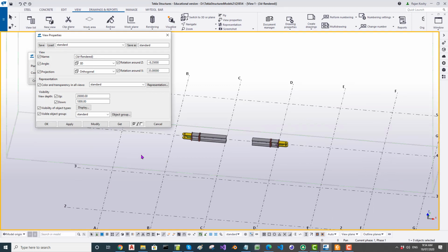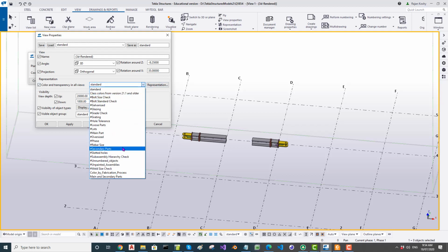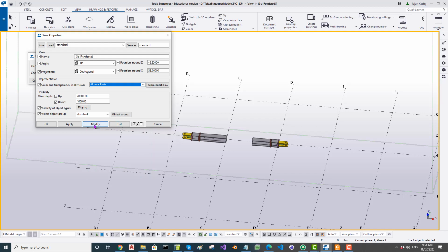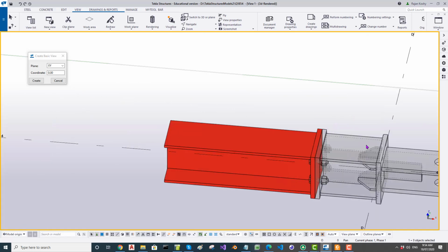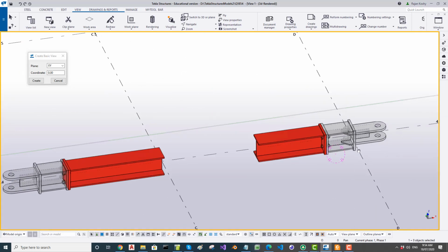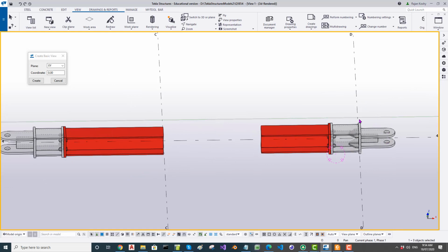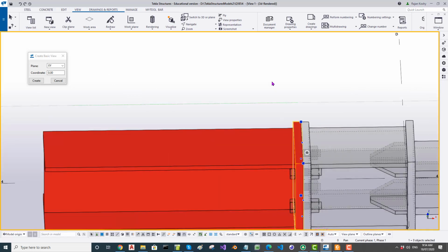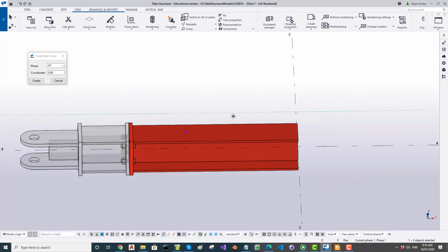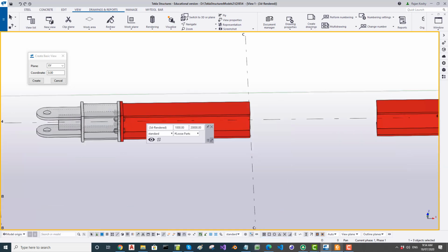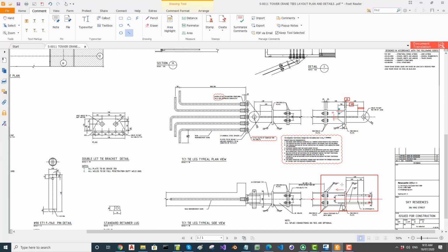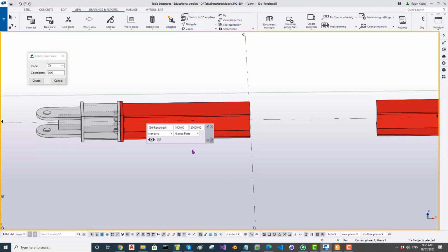Okay, to check for loose parts, basically loose plates, what we do is, see this button here, from here you pick loose parts and then modify the view. So whatever is loose means that's by itself, nothing assembled to it, will be red in color. So what is red in color? So there's nothing loose here, everything is welded together, but you can see this one is by itself, this one is by itself, this beam is by itself, and also this plate is by itself. So this plate, once we complete this model, will be welded to something. But right now that is loose. That's fine, no problem.